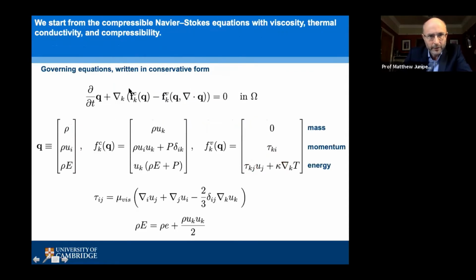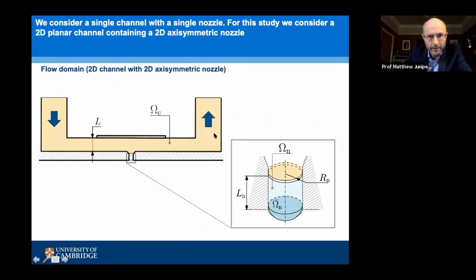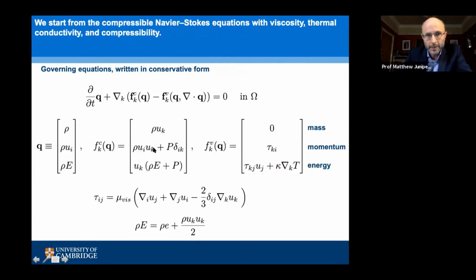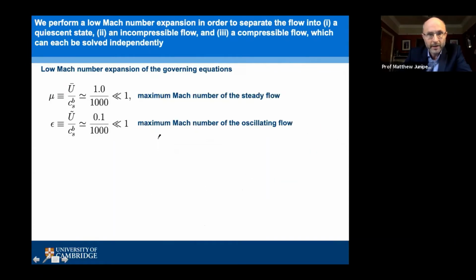Remember, there's a steady flow going through this inkjet here, which you can't ignore a priori. So let's consider that steady flow. It is a very slow flow; typically I put 1 meter per second, which is a large typical velocity in that sort of printhead. The point being, the Mach number is very small, much less than 1.